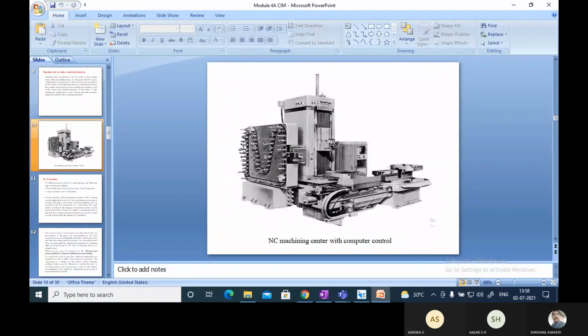So these are the tools. There are various tools kept here. Those will be called by tool station, not by diameter. You understood my point? You can see here, there is one drill bit. If it is at the nth station, TN will be given. That means the tool located in the nth station will be selected. That's all.